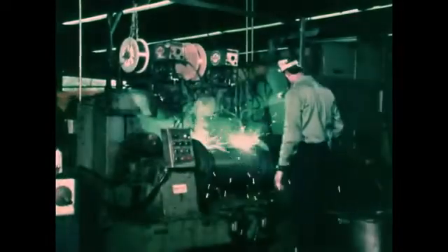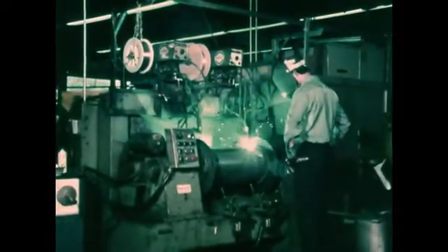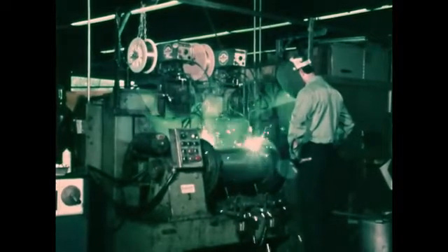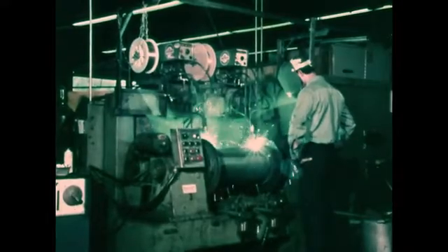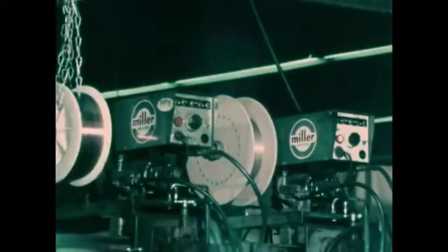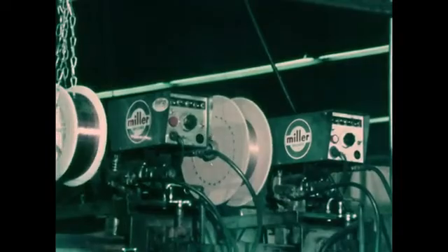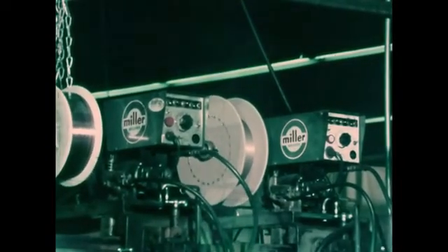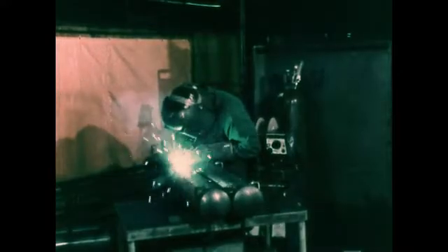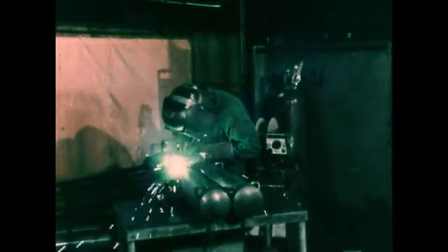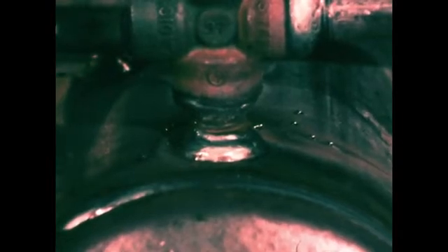The short-circuiting metal transfer method of electric arc welding is widely used in both large and small shops. It may be automated for jobs such as pressure vessel work, and multiple welds may easily be set up from separate wire feeders. Semi-automatic applications where both short and long joints are encountered, as well as awkward joint angles involved, are easily made with the process. Welds which must meet code requirements are made with great ease of repeatability.